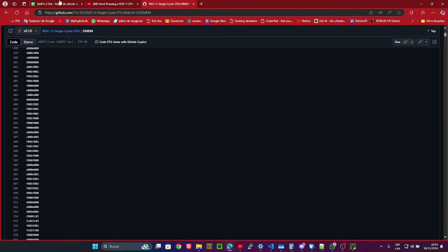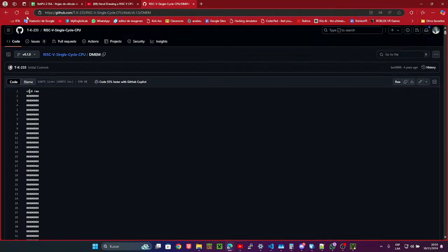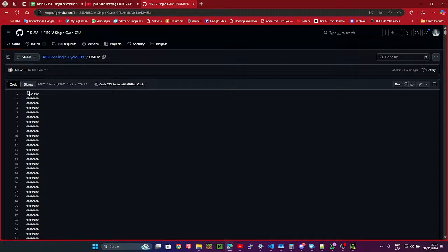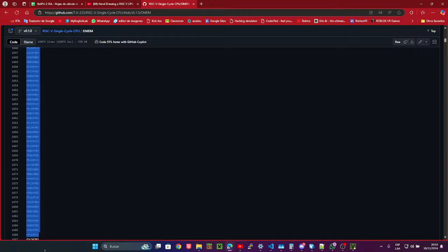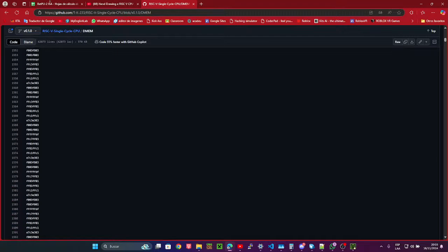In reality, standard VGA resolution is 640 by 480. Yes, it's 480p. That's how 480p exists. It's the standard resolution. But the width is 640 because the standard VGA is 4:3 aspect ratio. And they specify some timings for it.